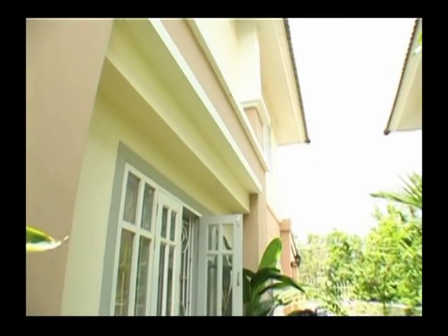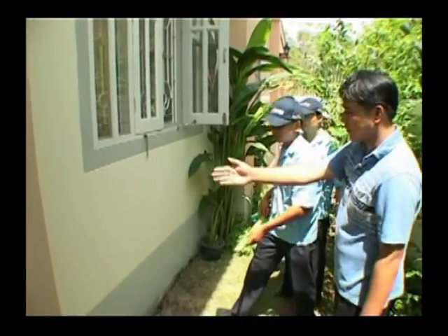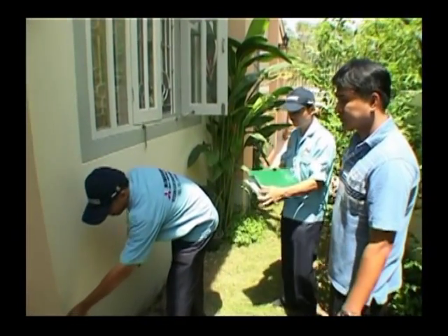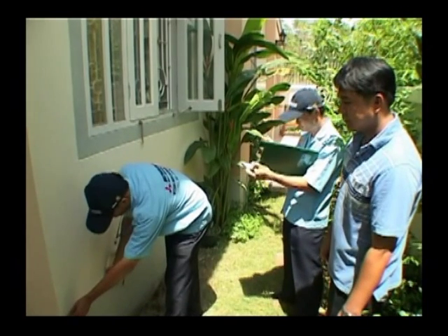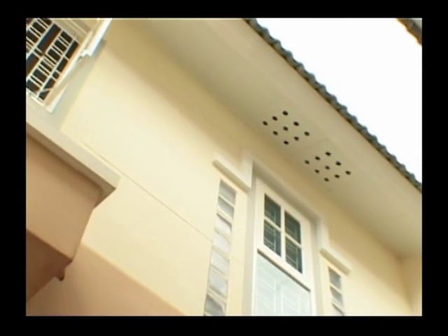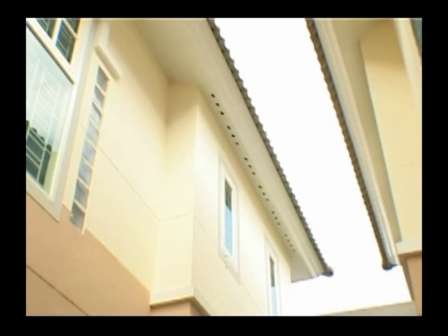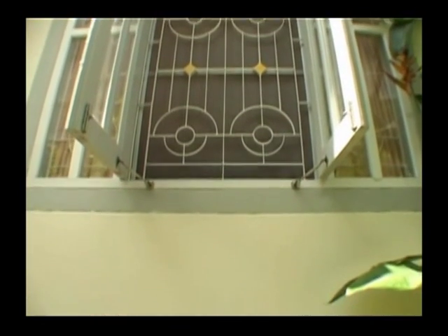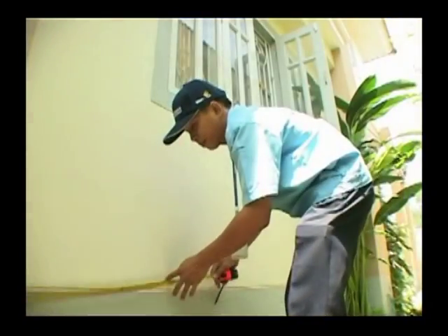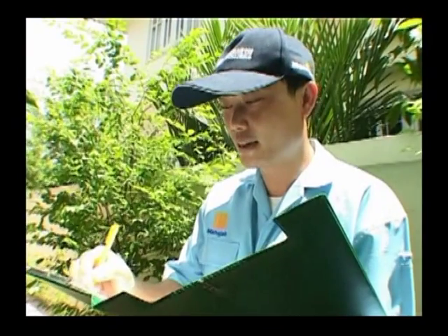For outdoor installation, a suitable location should have good ventilation and be protected from direct exposure to rain, snow, and sunlight. With a good location, an installed unit should be able to easily vent its hot air and its noise will not annoy neighbors. Also, there should be enough space for repair and maintenance and a fair clearance from vibration.